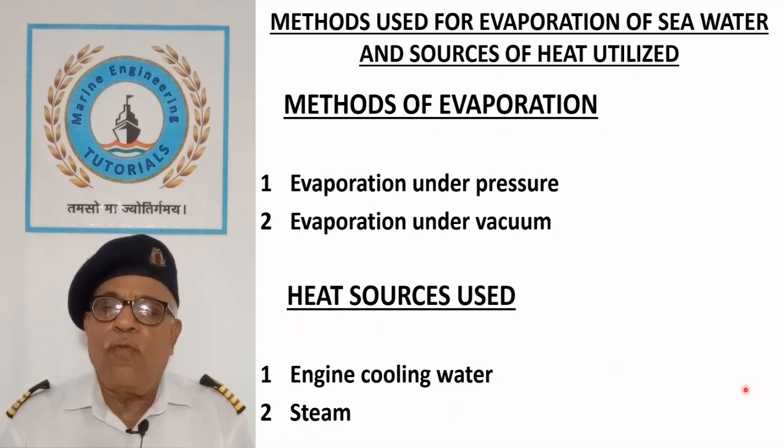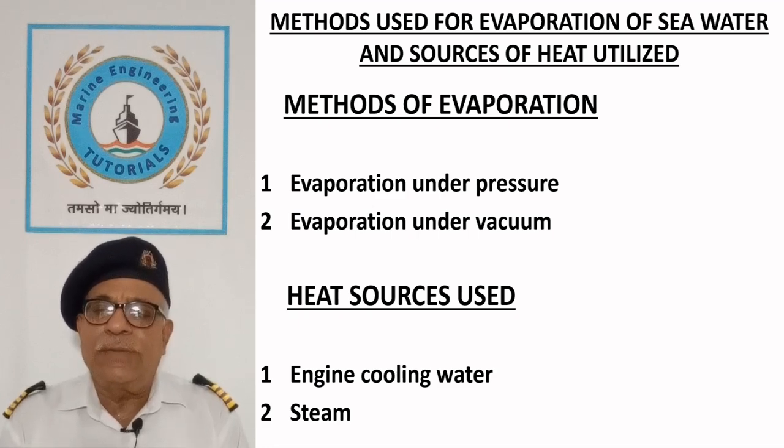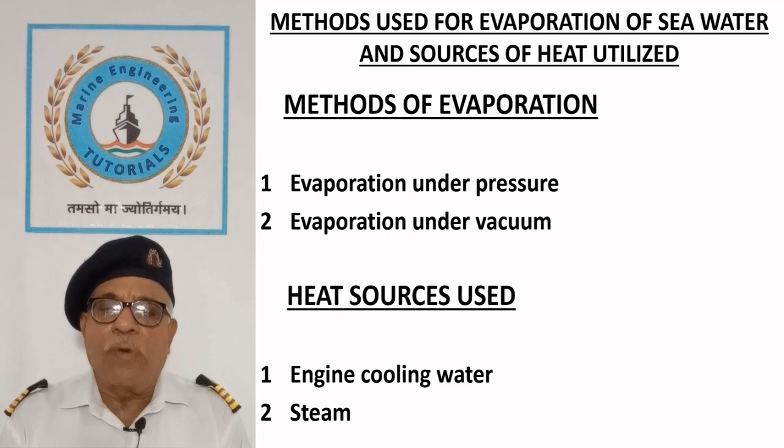Steam was the obvious choice for evaporation of seawater on earlier ships propelled by steam. Steamships mostly used waste steam as blow off or leak of steam for production of water. Some freshwater generators on diesel ships are equipped with arrangement of steam heating which can be used while the ship is in port. Being expensive, this method is used in extreme emergency.